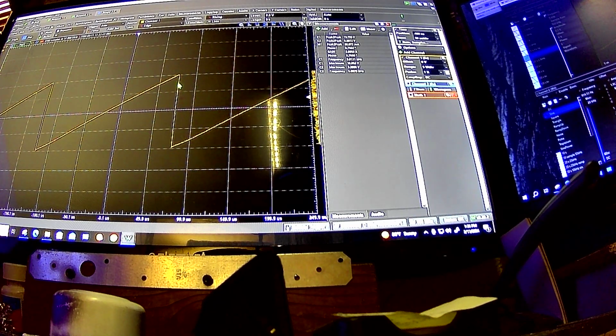It's got the same samples too, but the difference between these two waveforms is this big vertical, huge drop in slew rate. So this is how it's dealing with its desire to do an overshoot, because normally an op amp would probably overshoot in this situation at all these transitions. So, these sharp transitions, like on a square wave.